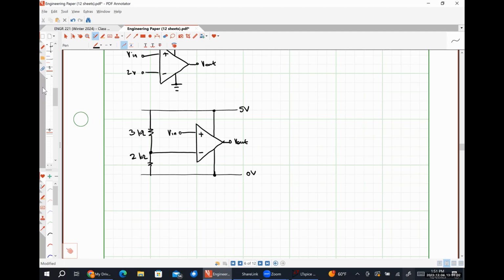Because let's see, the VX was 0. Anyway, if you're going to do the source transformation, make sure you're very meticulous about making sure that the voltage VX is defined between the same pair of nodes as it was defined originally. Because this would give you a 30 volt source, but because VX had positive over here, the sign is changed.